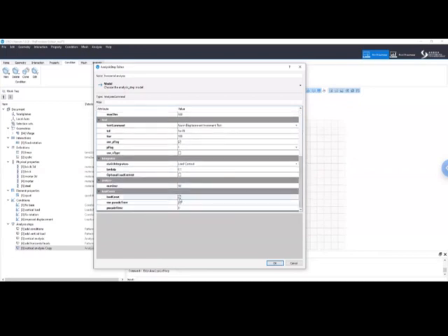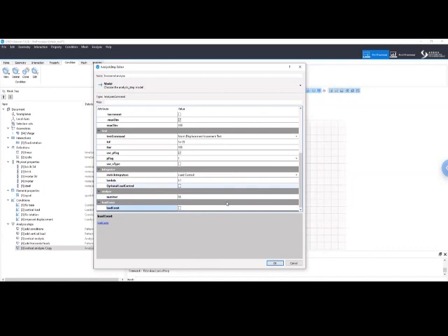We don't need to put the load constant because in either case, this one will be the last analysis. And we're going to use 1e-3 increment, and we want to use 1,000 increments. So basically, we do 1,000 steps at 1e-3 delta increment, so that at the end of this analysis, we will reach a time step of 1, so the complete time series for the cyclic load.